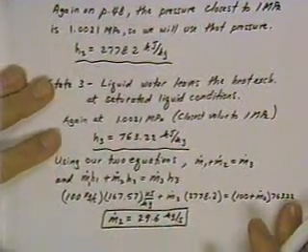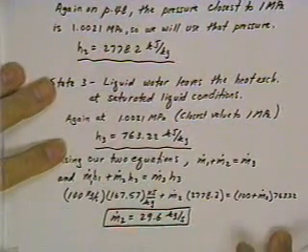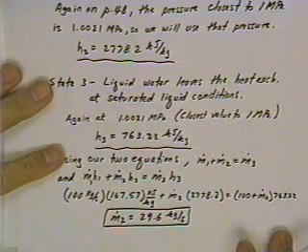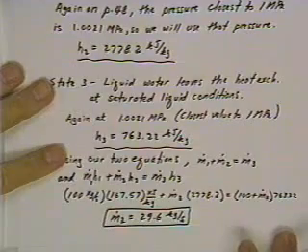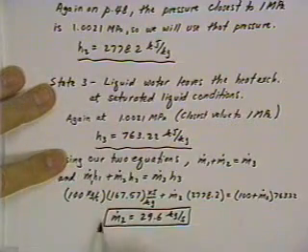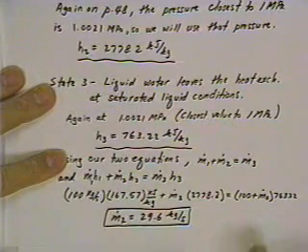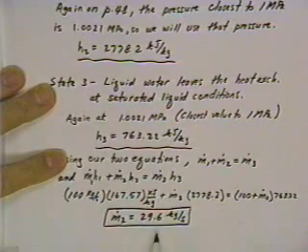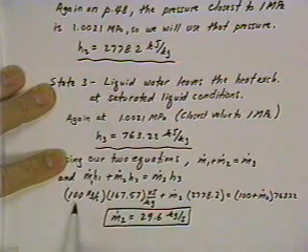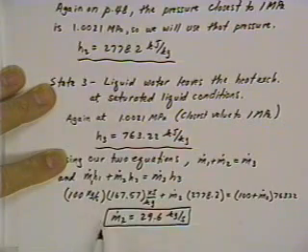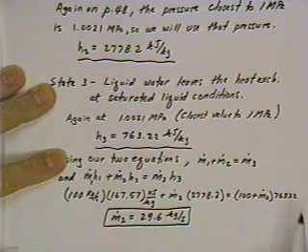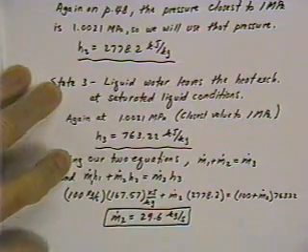So if you solve this equation, you can go through the algebra. I hope I've done the algebra right, but you can check me out as you verify these numbers. But you get from this m.2 is equal to 29.6 kilograms per second. So for this particular problem then, it takes 29.6 kilograms per second of steam to mix with the 100 kilograms per second of water to raise the overall energy of the leaving water up to an enthalpy level of 763.22.